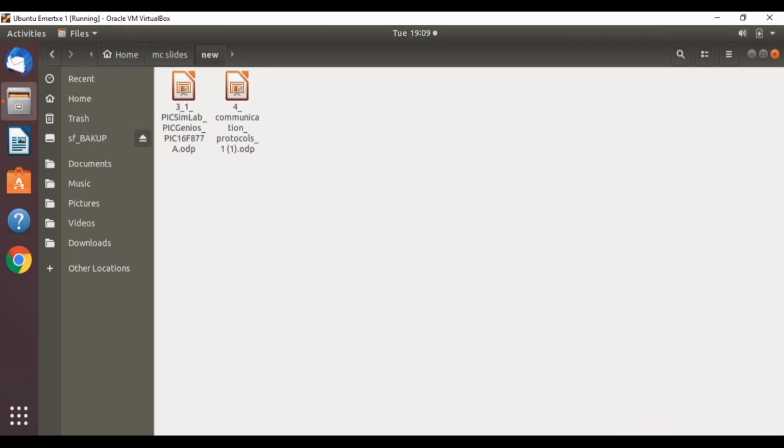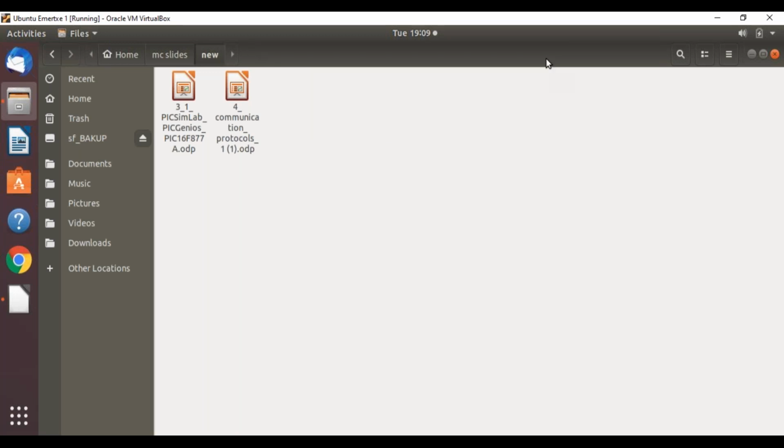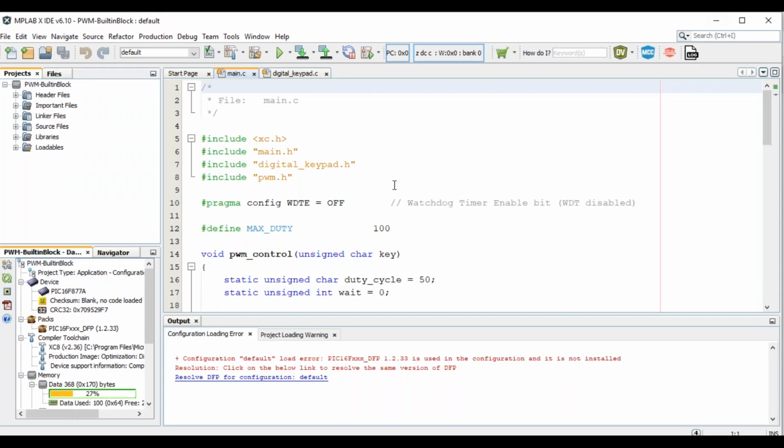We initially made the modulated waveform glow with a 50% duty cycle, and after that, whenever switch 1 was pressed, the duty cycle was increased, and when switch 2 was pressed, the duty cycle was decreased. So that is what we discussed in the previous class.